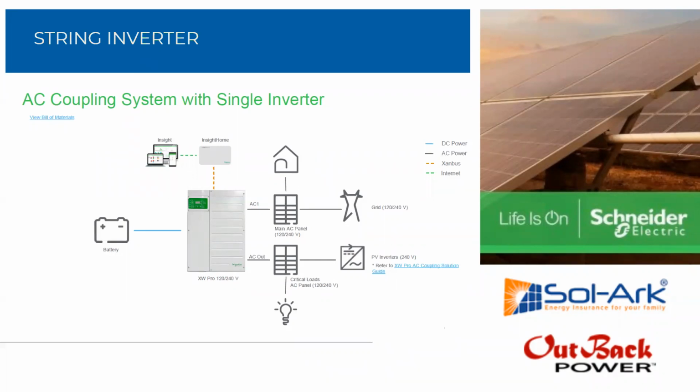With the advent of load control, this works in a few different ways. Our different brands are approaching load control in different ways. So Enphase has these contactors where you can add 2 breakers with relays on them on your main service panel. And let's say those are feeding your air conditioner and your clothes dryer. We can put all of our N-Charge batteries now on the main service panel, but with the addition of these contactors,